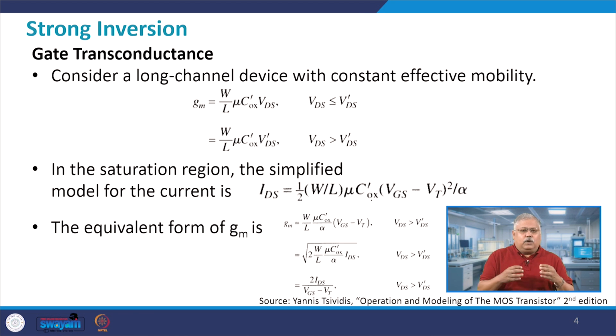Similarly, if you have strong inversion and you want to find out the drain conductance, then the strong inversion drain conductance will be relatively low because your channel has been formed very easily and therefore the resistance will be small. But at weak inversion that is not the case, and therefore it varies. The gate, drain and bulk conductances vary as you apply the bias and move from linear to non-linear to saturation, as well as from strong inversion to weak inversion to cutoff.